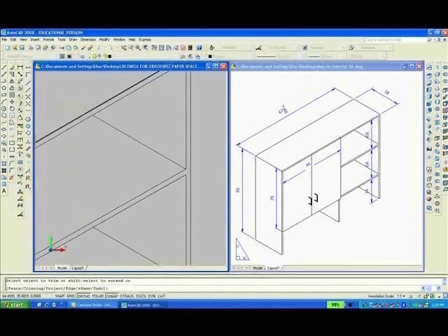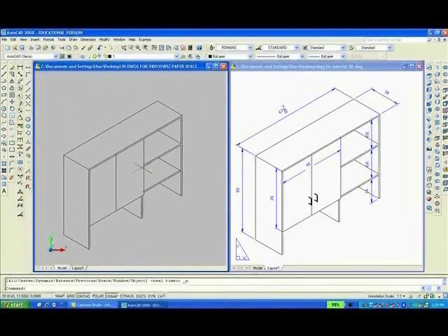Zoom previous. We have one more chore to do, so I'll hit the F5 key again and again, and I'm going to type, I will select the polyline, and I'll pick any point here like that, and I'll type W for width, 0.25, enter, enter, so it's 0.25.